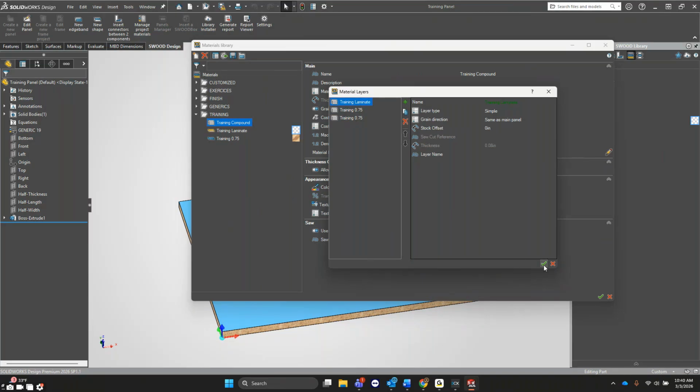So everyone good with that so far? Would that be good for, like, here we'll order particle board at 11/16 and then order laminate top and bottom. It'll be pre-finished for us, but is that good to use a compound, or do you think I should just use a generic panel when we order stuff like that? So you're saying it doesn't come glued up and you glue it up yourselves? Well, it does come glued up, but we have to order it in a very specific way. Because if we just say, I want a 3/4 inch panel with laminate, they're going to send us a 3/4 inch core panel, and then it's almost like 7/8 thick.